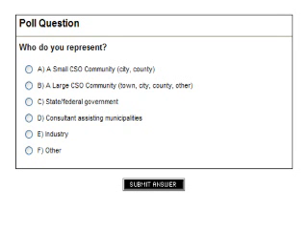Mark, I just want to tweak the question a little bit. When you are designing the deep tunnel, are you considering the leakage of the water? Do you need to consider the leakage of the tunnel itself? In Atlanta, it's very little, and no, I don't think they considered it in the design of the volume for capture in that tunnel. They designed that tunnel to capture a certain amount of overflow. It was 187 million gallons, and they start pumping out right away. They were able to cut out about $125 billion in tunnel costs by pumping out almost as soon as the water's coming into the tunnel. So they actually reduced the tunnel size somewhat, but they didn't consider any leakage from the tunnel in the calculation of that required volume.